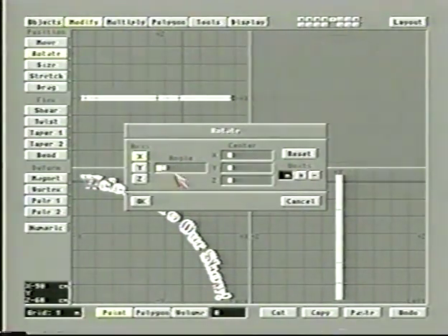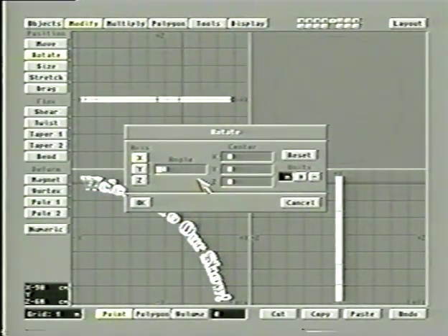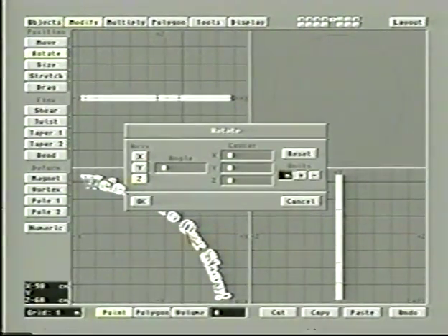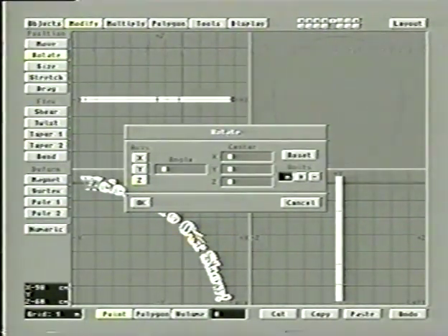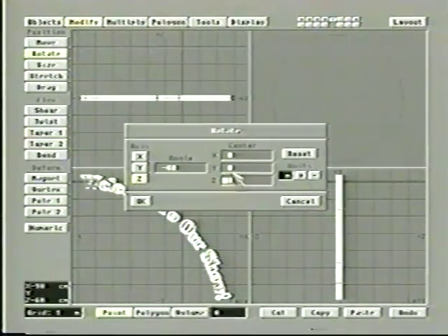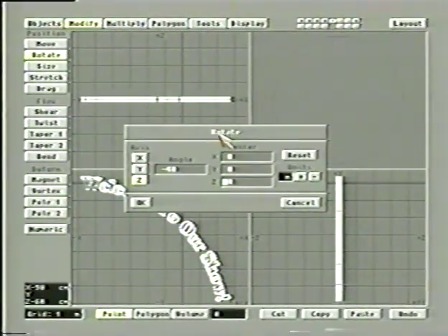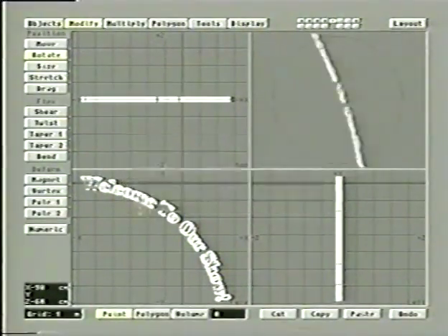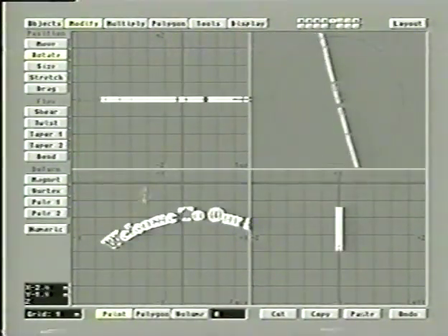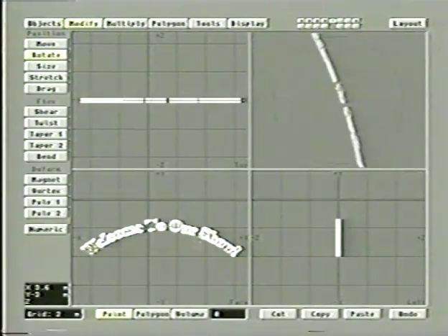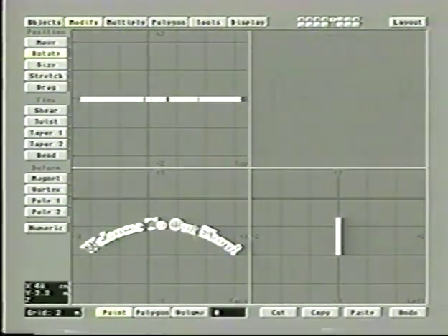and since we did an 80-degree angle of bend, what we need to do here is on the z-axis. In other words, it's pushing through here, moving through the center. We need to give it a negative 40-degree angle, because an 80-degree bend needs a negative 40-degree rotation. Same center as we had set when we did the bend function. Remember, when we used bend, our center was 0, 0, 0. What we have here is a nice evenly distributed curve now.